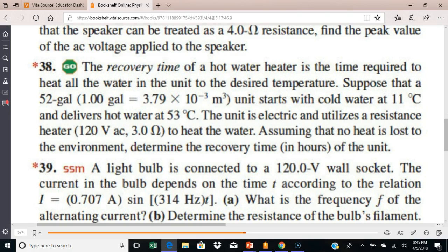Okay? So C delta T, specific heat is 4186 joules per kilogram degrees centigrade. Mass of the water. I don't know what the mass of the water is, do I? But I know density of water is equal to mass divided by volume, and I've got the volume here.